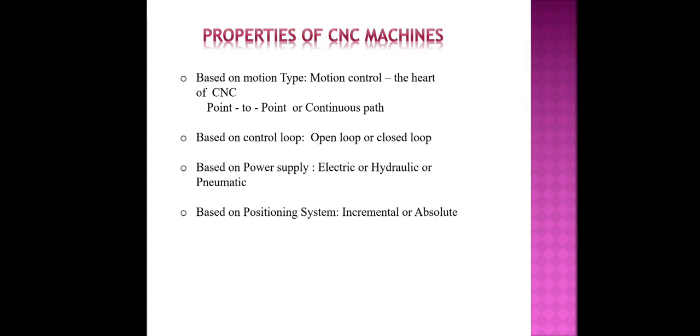In a closed loop system, there are feedback subsystems to monitor the actual output and correct any discrepancy from the programmed input. These systems use position and velocity feedback, and the feedback system could be either analog or digital. In a closed loop system, the analog system measures the variation of physical variables such as position and velocity in terms of voltage levels. In a digital system, the output variation is monitored by means of electrical pulses.